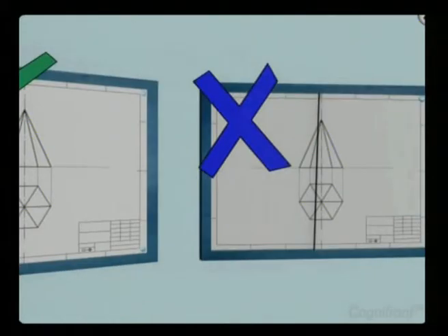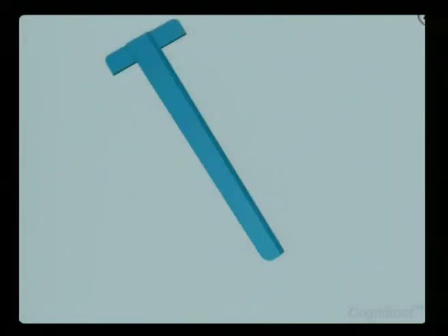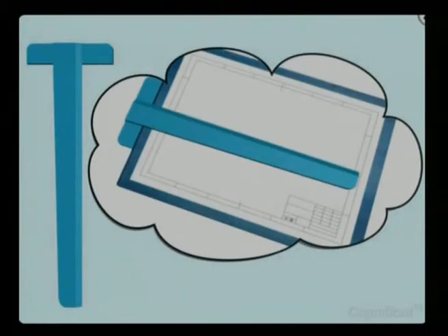The drawing board is a plain and smooth surface used for drawing purposes. The ebonite edge of the drawing board facilitates smooth movement of the T-square. The T-square, as the name suggests, is a T-shaped drawing tool. Its straight edge slides along the width of the drawing board with the help of a stalk. It is useful in drawing straight lines and also serves as a supporting edge for set squares while drawing inclined lines.